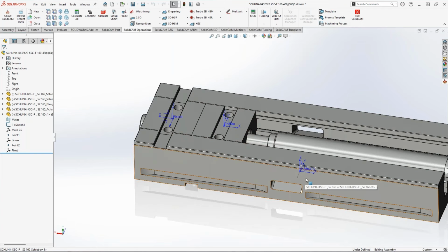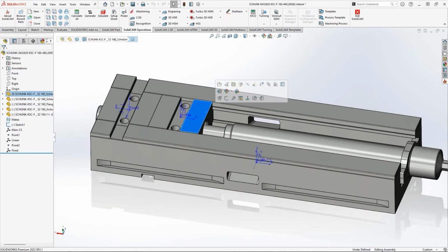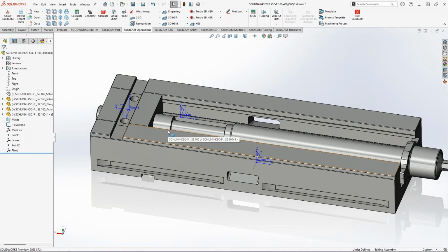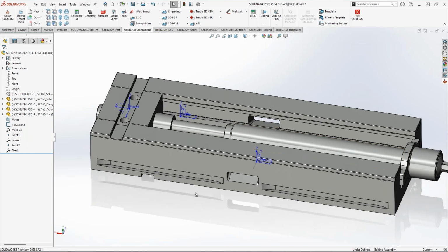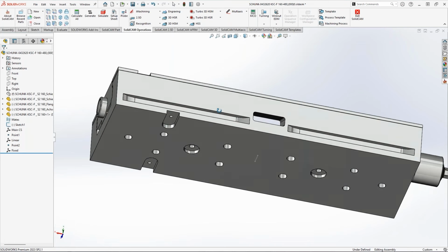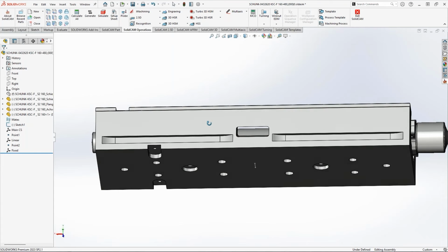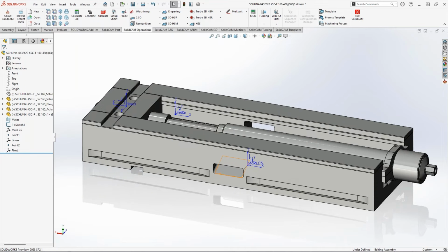These are the 3 coordinate systems that I need for a vise. So let's export those things. I'm going to hide this body over here because this is going to be exported with another model. Everything that you can see here is the main body. So yes, you could have screws, maybe more complex vises. I always advise that the fixture manufacturers usually provide some kind of geometry optimization, so it's not so heavy for the simulations.